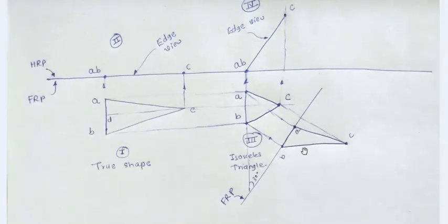So even though the problem is typical and slightly complicated, the number of points need to be projected is less, and this would be the generally case. In earlier problems we had pentagon or hexagon where 5 points, 6 points needed to be projected, but in this problem we needed to project only 3 points, but this less amount of points needed for projection is compensated by complication at this stage. So always remember, you can by heart also, isosceles triangle can be seen in the change view as equilateral triangle, and we have to find the inclination.